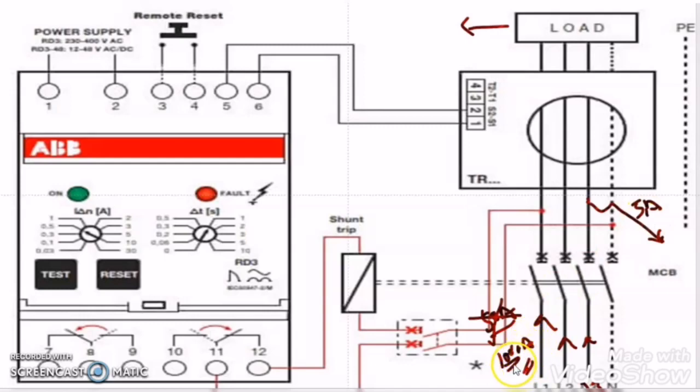And in another case, now the total load current is 1000 ampere from each phase, then the leakage current will be more. Suppose this time 50 ampere of leakage current is flowing at earth leakage fault condition. So this time also the CBCT will find the difference in each phase, but this time the CBCT will encounter a higher difference in the phase current compared to the first case.